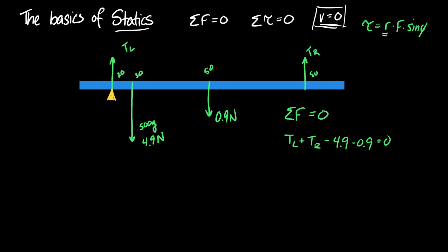And more importantly, if I put it on one of the unknown torques, I eliminate an unknown, making the math easier. So if you can, this is a hint: if you can eliminate a torque by the placement of your pivot point, you should do so, especially if it's an unknown.